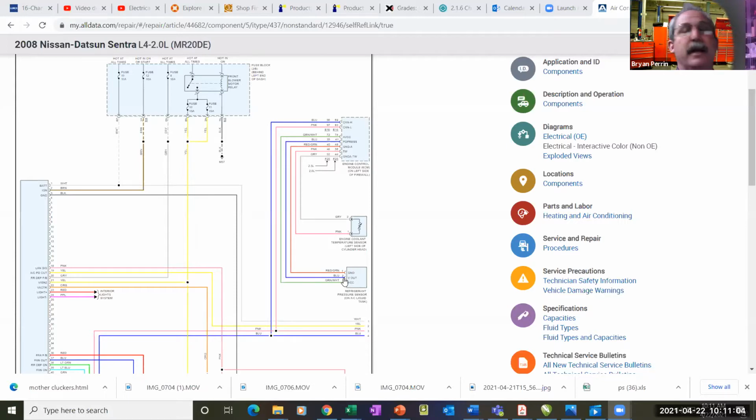But just unplugging it, what does your data read? Because unplugging it should go to 5 volts. That may let it come on, but it probably won't, because it's probably not going to come on if you're down close to 0 or too close to 5. It probably wants to see something in the middle. That's probably fairly easy to get to. But I'm almost positive it won't come on if it's unplugged. Maybe that got knocked off, unplugged, broken wire. Who knows?